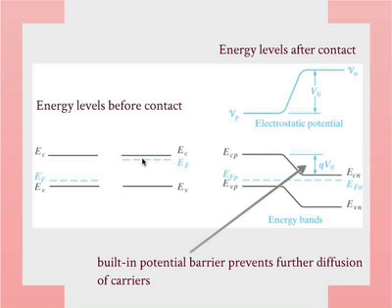Of course, when they're in contact, remember we talked about the Fermi level cannot change in space. You cannot have gradients unless an external potential is applied. We will see again, but it has to be constant. So when you put them together, the Fermi level has to be flat, which means that the two bands have to bend on two sides. So you have a bending of the conduction band going down, a bending of the valence band going down, and this bending difference between the conduction band on the P side and the conduction band on the N side is the contact potential. That is the picture. Now we'll calculate this, but that's the picture I want you to keep in mind, okay?